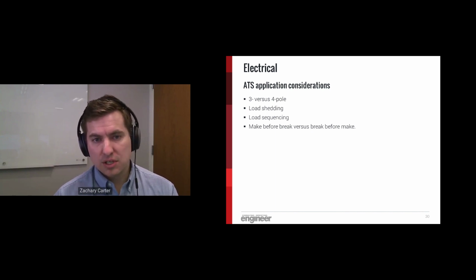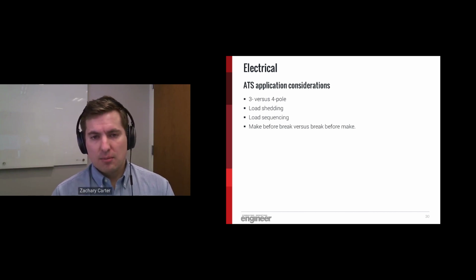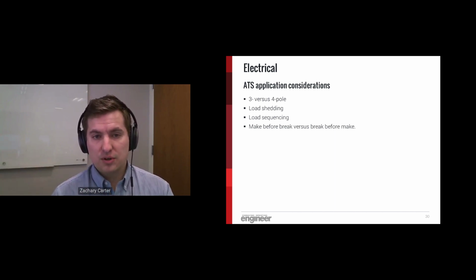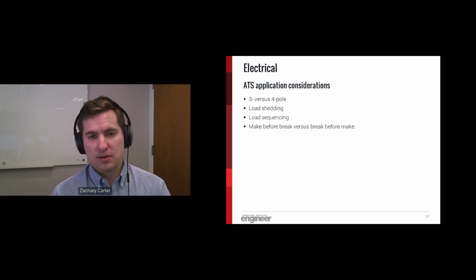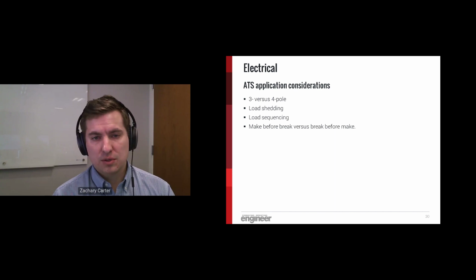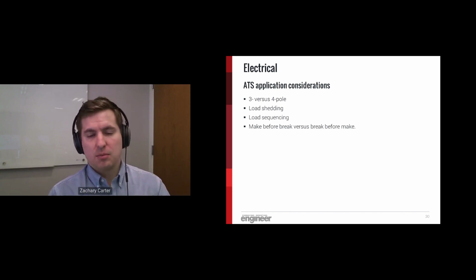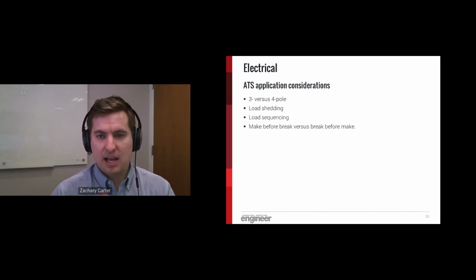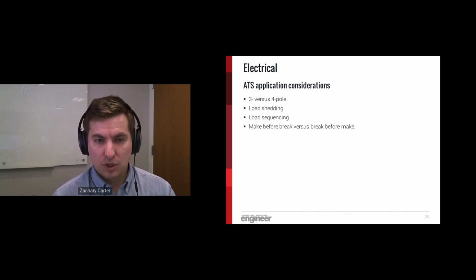Load shedding or load sequencing, you'll hear a lot, right? Let's say that we have a generator where we need to take loads off of the generator because we need the generator to carry some loads a little bit longer, or simply the generator is getting overloaded. We'll specify a transfer switch with the ability to shed the load off, or load sequencing or load stepping. It would be vice versa in case we need to step load, or we realize that we have more capacity within the generator, we can add that optional branch on the generator. We have load sequencing or load stepping